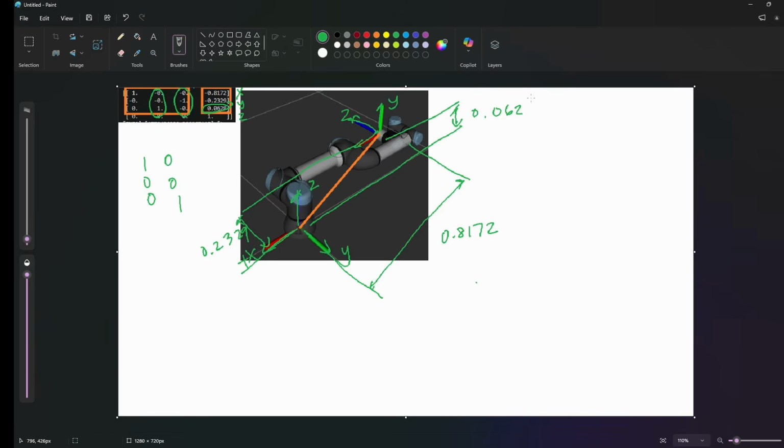And the idea is, our forward kinematics can take in any angle and will output our transformation matrix. Right now, our current angles are at all zeros. But you could repeat this process by updating the angle, say, from theta 1 to theta 2, like, for example, at time 1 or time 2. You could have a different vector for the thetas, and then you'll have a new transform that describes the new tool end. So that concludes the summary for kinematics for our robot. And in this specific one, we were just using the URDF frames that they got from ROS.